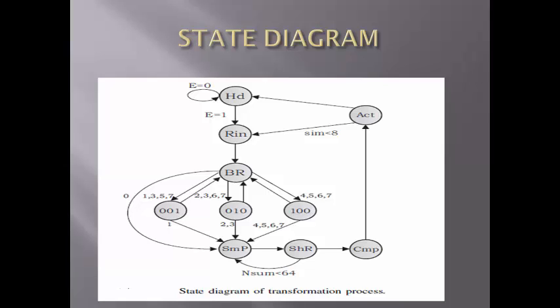The values of the registers, minimum distance and final symmetry are updated, storing the identification of the transformation with least distortion. The 4-bit counter symmetry identifies the transformation performed. If its value is less than 8, then it moves to the state RIN, otherwise processing is done. We show the registers and signals that form the interface.